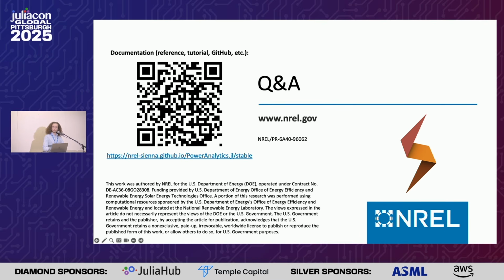Hi, thanks. It's interesting to see a discussion on power system and analytics here. I don't see much discussion on, let's say, the shadow prices, or just dual variables of the constraints of the simulation model. So I'm wondering if that's part of the analytics, where the metrics that users are defining, or is it a feature request? So the simulation certainly outputs those duals, and so they're there for metrics to grab. I believe our total cost metric does grab a dual, and in general you can certainly define metrics that key onto duals. Cool, thanks.